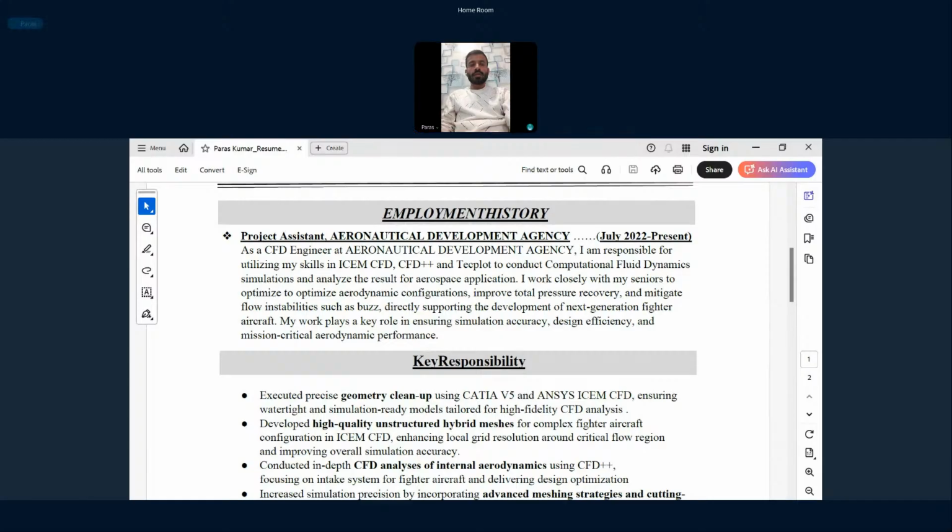So in this part, at the intake duct exit, we have an AIP, which is the aerodynamic interface plane, which is at the engine face and at the exit of the duct. At the AIP, we give the boundary condition, like I am giving the mass flow rate outlet, which we previously calculated from the engine mass flow rate given to us. So at that particular mass flow rate, the CFD will analyze the AIP total pressure at the mass flow rate we are giving at the engine face.